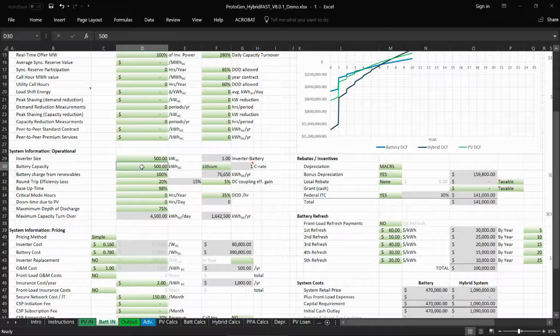And this becomes important because if you had a situation with maybe a lead acid battery and you're only allowed to kind of take off the top, you may run into situations where, oh, well, you're not allowed to do that based on your revenue streams, or the calculator is trying to utilize revenue streams where now you're not able to discharge deep enough. So that once again creates another battery alarm.